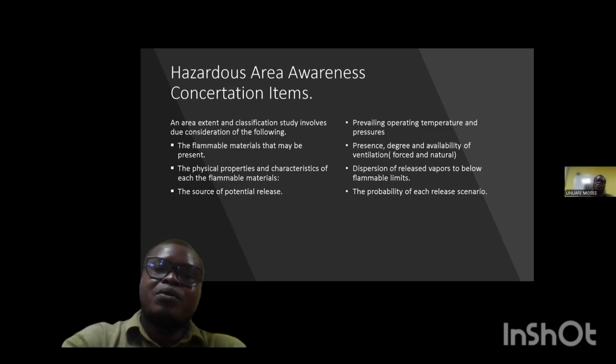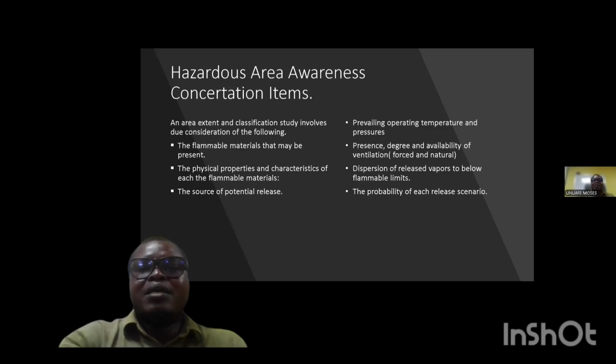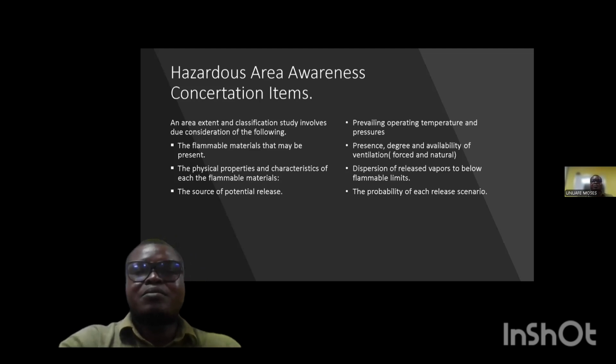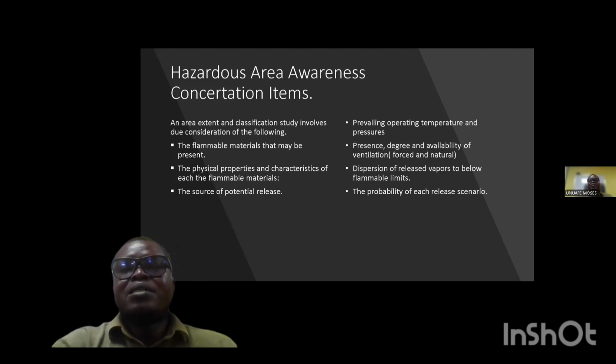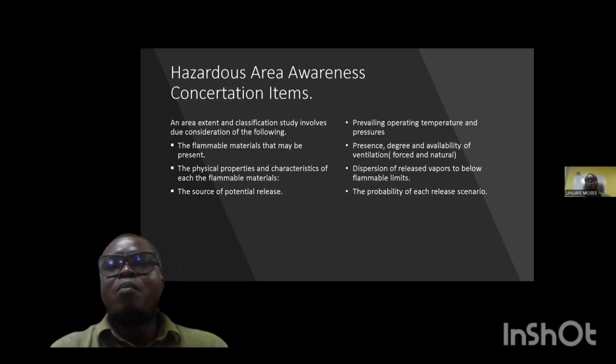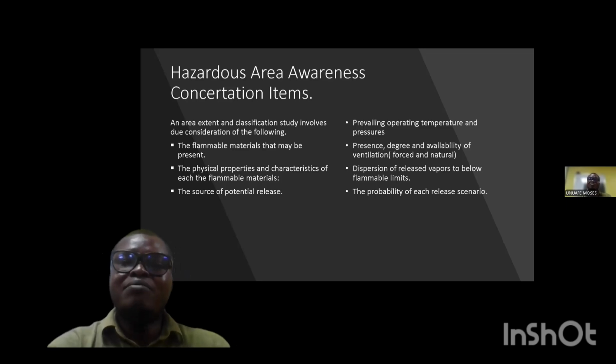For example, let's say you are working with a natural gas compressor in a process plant. During normal operation, the compressor casing constantly reaches 65 degrees. Although it may spike to 80 degrees during startup or drop to 40 degrees during shutdown, we are going to pick 65 degrees as the prevailing operating temperature.